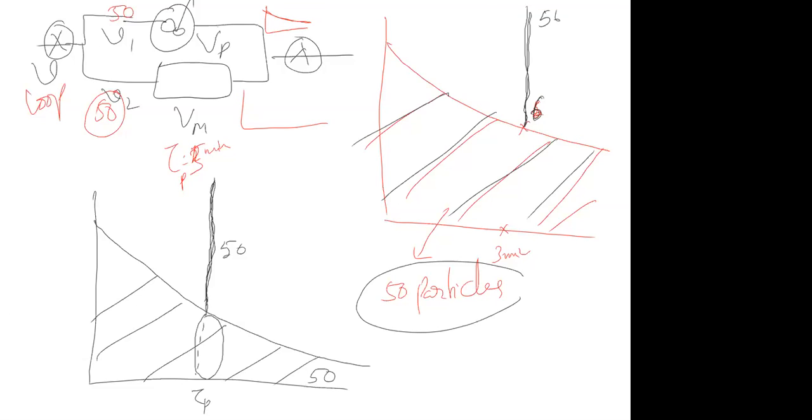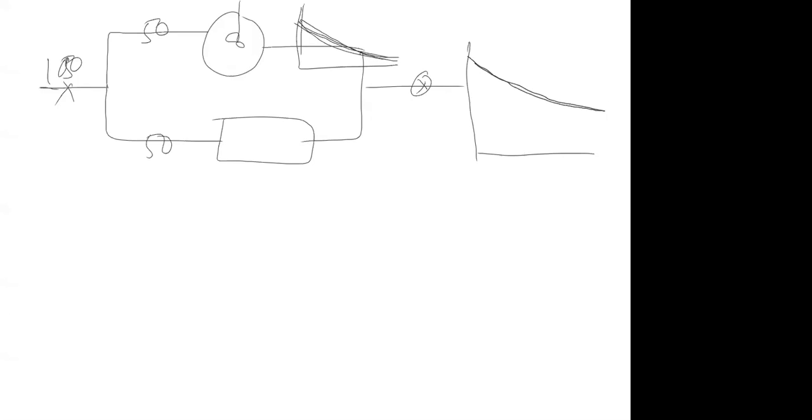So I'll repeat again. Let's take a CSTR and PFR in parallel. Let's say I injected 100 particles here. 50 go this side, 50 go this side. The 50 which go to the CSTR will come like this, immediately, directly here. Imagine that there is no PFR. Whatever the 50 that go here will come like this. The area under this curve corresponds to 50 particles.